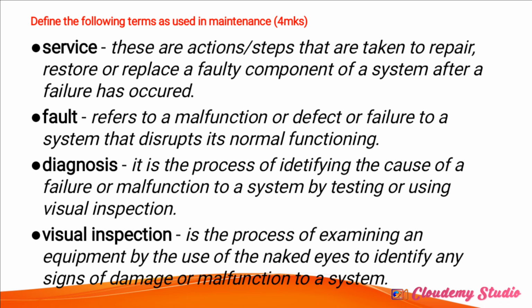So I said you might find that you are using a charger. The charger is rated 3.1 amperes, but when you use the multimeter, it is giving out 1.5 amperes, half of its rated capacity. So even if you have your load, which is the phone, you are charging it, it will take a very long period of time for your phone to be full. So that charger has a fault, and it's not a total fault, it's a partial fault. The system is working, but not according to its expectation.